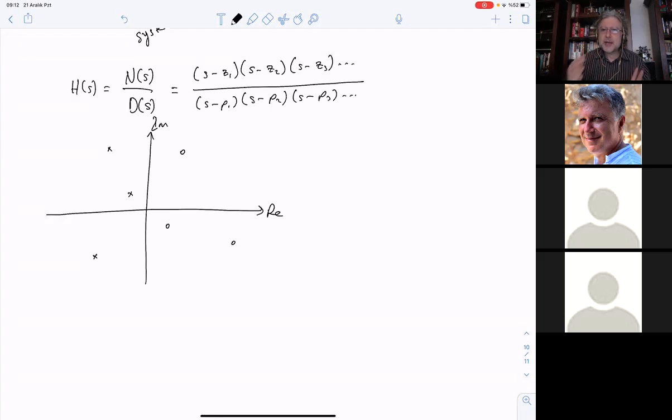It is so much an assumption that even the definition of the Laplace transform has evolved to the definition where the integral starts from 0 and goes to infinity. It's not from minus infinity to infinity anymore for physical systems because of this right-hand sided assumption, and the stability is therefore requiring us that the poles are on the left-hand plane.